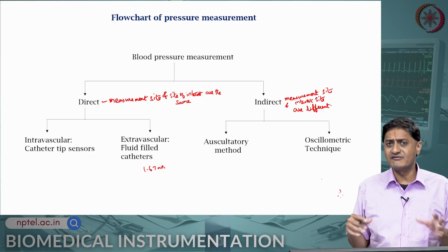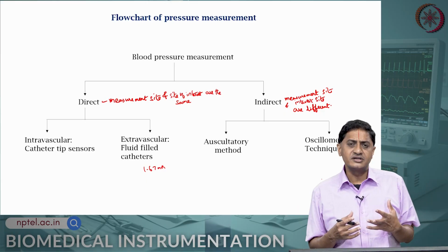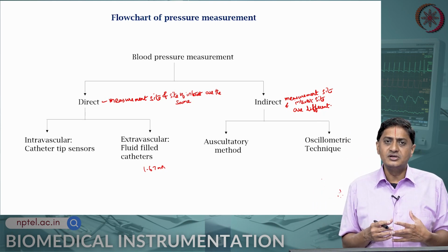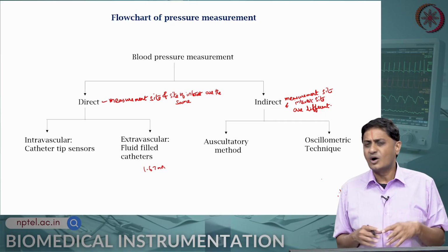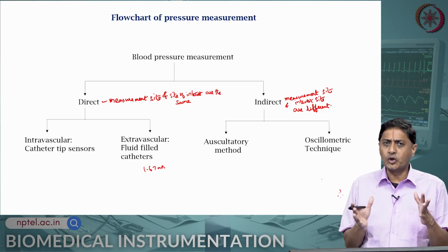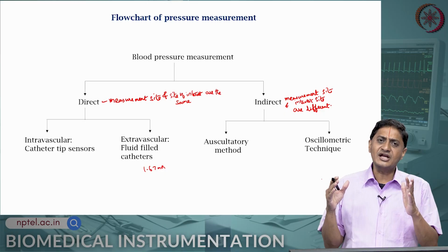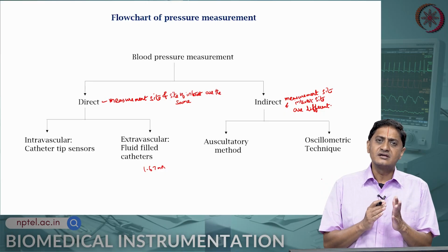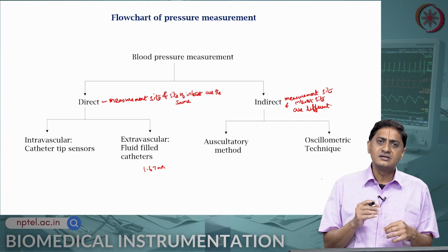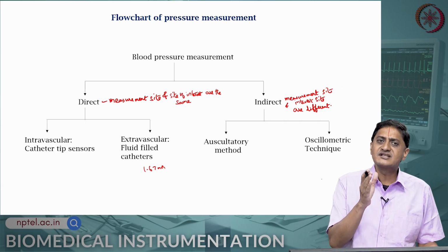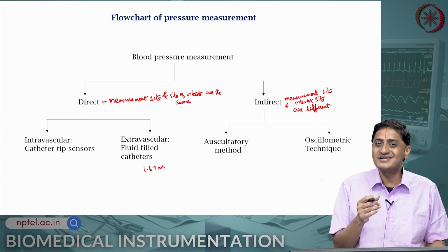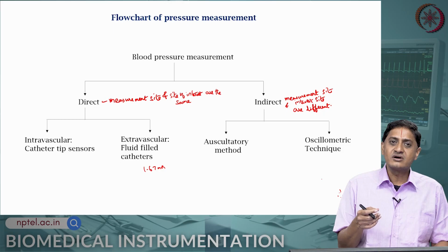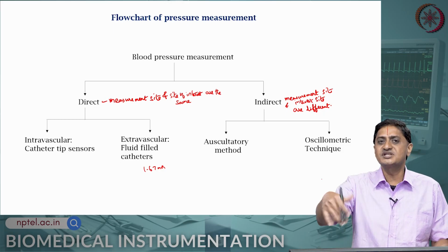Let us assume that I have a method to convert that pressure into an electrical signal. How is this achieved? Essentially Newtonian mechanics. So, the interaction of fluid on the solid, or the not a rigid body, flexible diaphragm essentially causes deformation of the diaphragm, which causes a change in some physical quantity of interest.